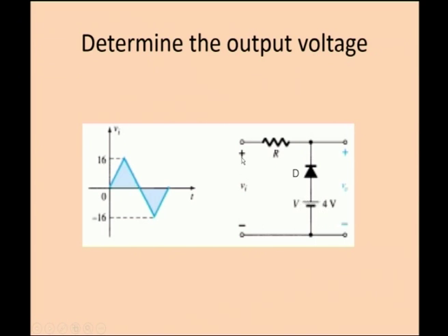So, you can increase the input signal voltage. If you increase the input signal voltage more than the voltage applied to the anode terminal, then the diode will be in a reverse biased condition, and then the diode will be in open circuit and the output can follow the input. So, if the input voltage is more positive than this DC voltage, then the diode will be acting as an open circuit.